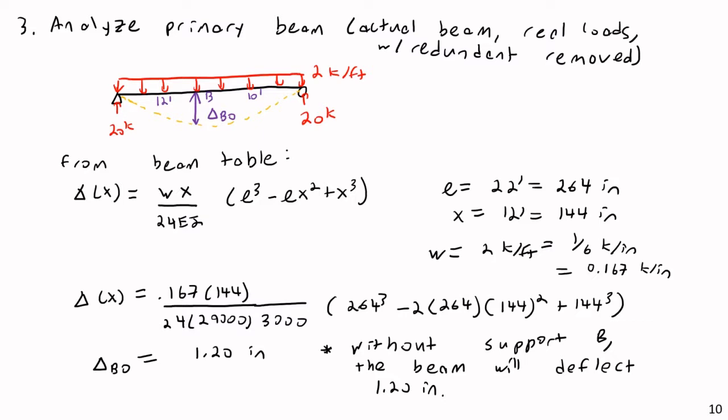If I convert that 22 feet to 264 inches, times 12, so 1.2 over 264, does that meet our 1 over 240? Not quite. So it may actually exceed a deflection limit, depending on what kind of deflection limit you're using for your beams. But really, that's not too bad of a deflection. I'm not sure I would bother building a middle pier. Although maybe they had that middle support for strength rather than for deflection. Or maybe that middle pier exists because this is a contrived example. I guess we'll never know.